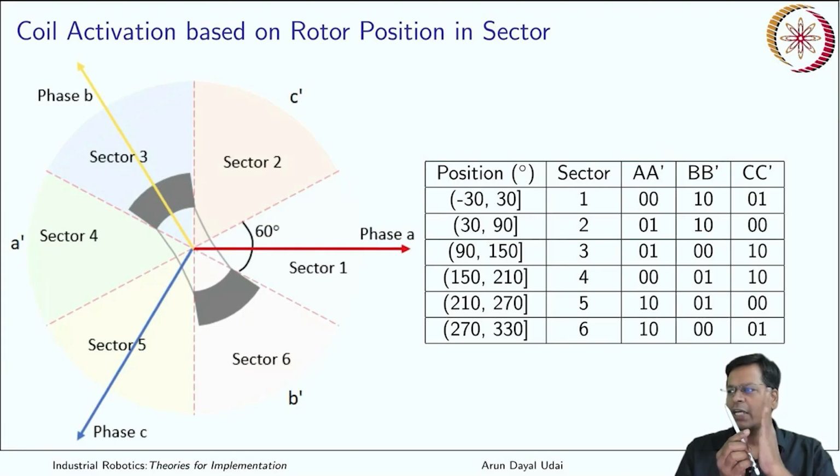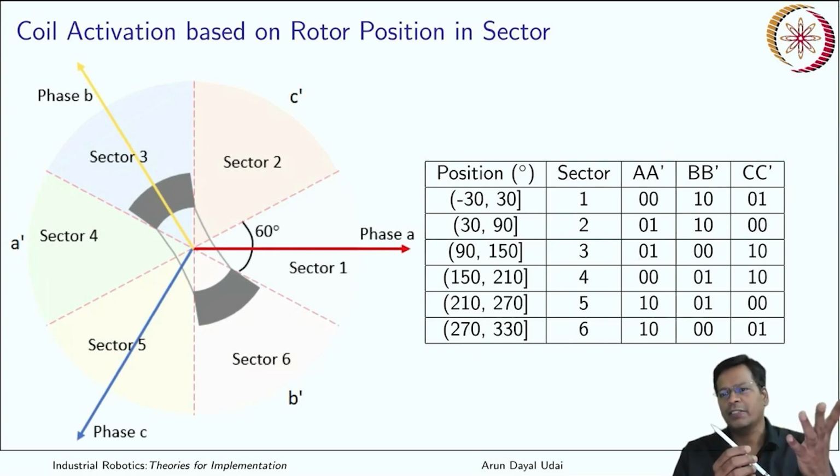If it aligns, I will put another target. It will again align with this. Another target, align with this. Another target, align with this. So that way I will keep on rotating my magnetic field based on the current status of my rotating armature. Wherever it is, it will give you a new target in the direction where I actually want my rotor to move.